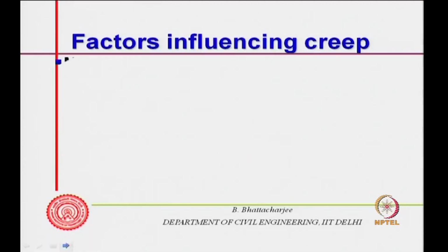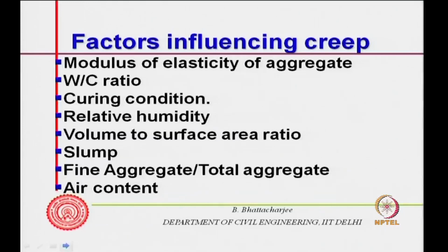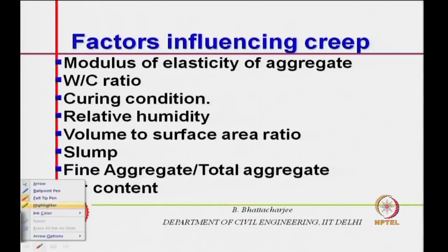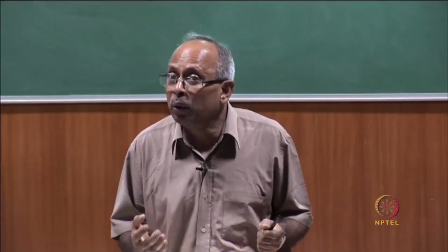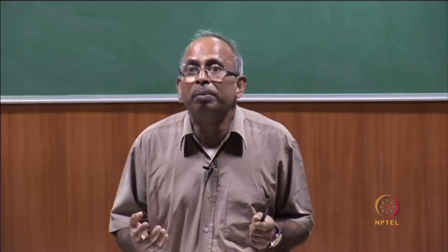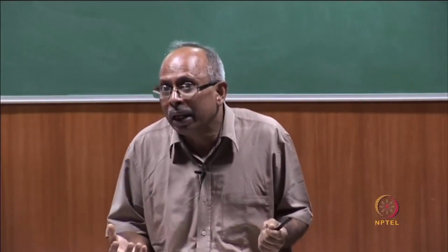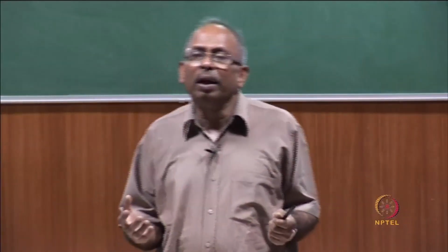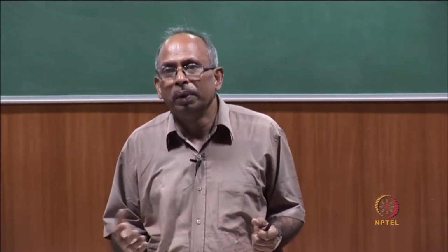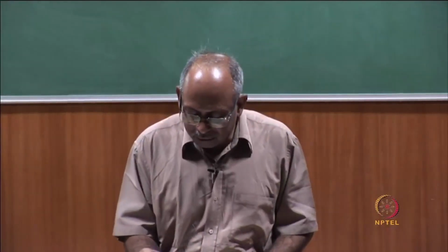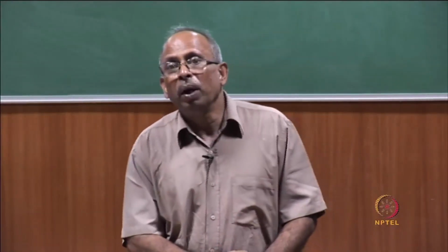Let us see what are the factors that influence creep. First of all, modulus of elasticity of aggregate. We will see more of it, but we can understand that the deformation of the concrete would be affected by the modulus of elasticity of the overall material, and in the overall material the aggregate modulus of elasticity plays a role. Therefore, modulus of elasticity of aggregate is an important one.